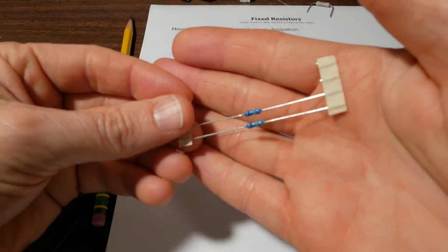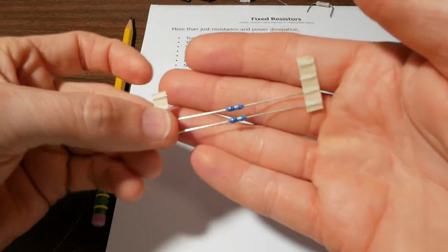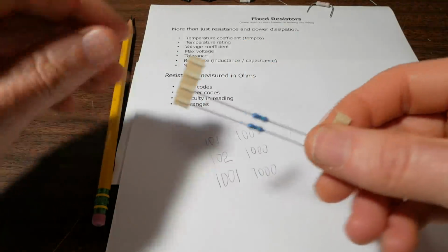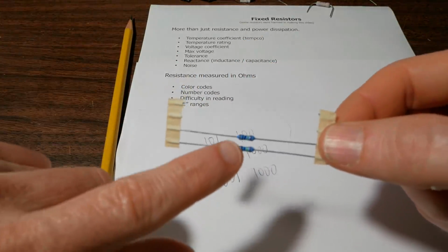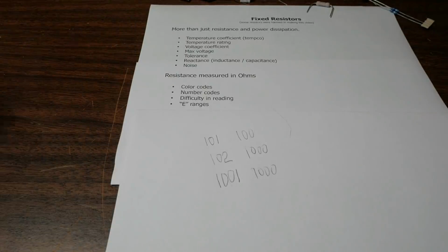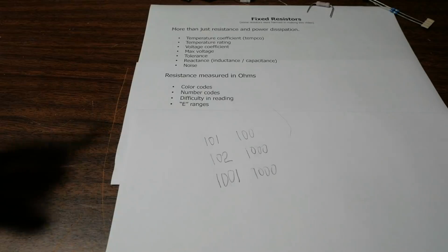It's very hard to read the colors on the blue metal film type resistors. Also, you have to be careful of the tolerance. For example, brown, black, red is normally a 1K resistor. With a precision resistor, it would be brown, black, black, brown, because you're only adding another 0.